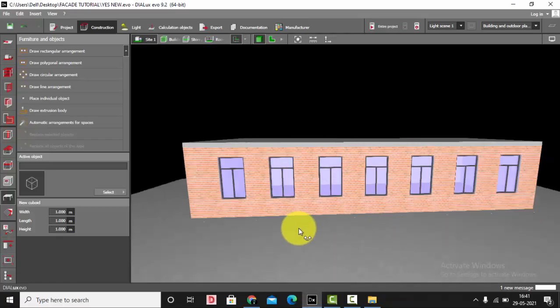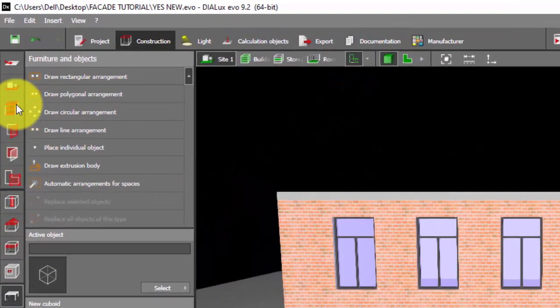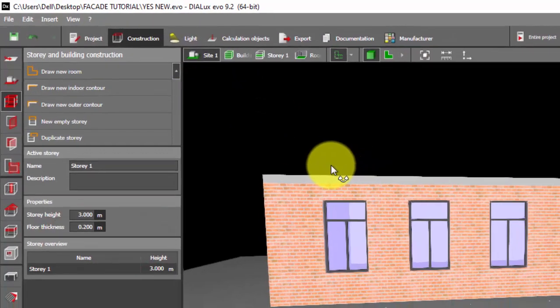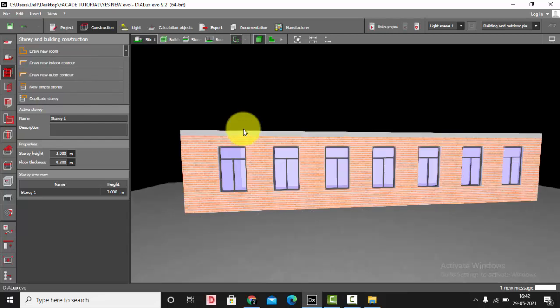Now coming to my building, the building height is 3 meters. Since the building height is only 3 meters, I think we can use uplights with low wattage, because another point of considering the wattage of the uplights is that I don't want the light to cause light pollution.